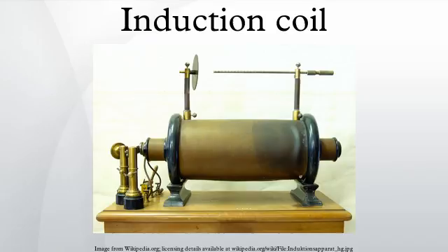Capacitor. An arc forms at the interrupter contacts at break, which consumes energy stored in the coil, slowing the rate of change of primary current, reducing the output voltage. To prevent this, a capacitor of 0.5 to 15 µF is connected across the contacts to increase the speed of switching on break, producing much higher voltages. It also prevents damage to the contacts by the arc.